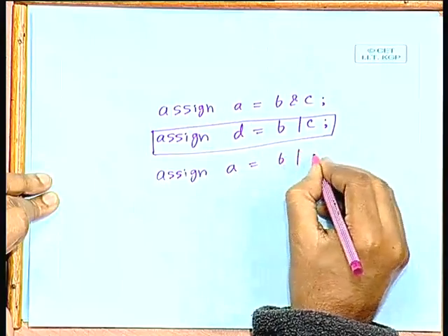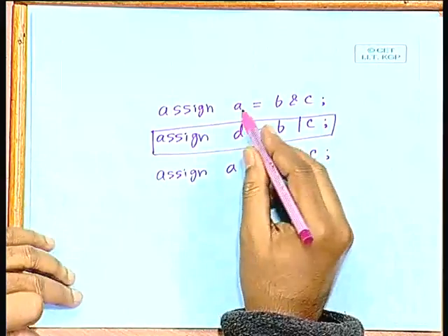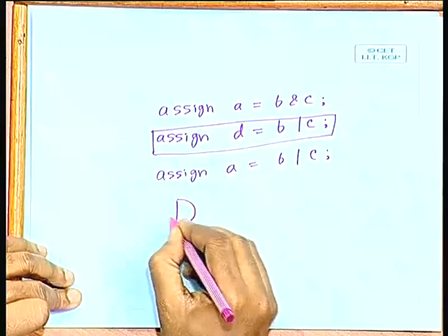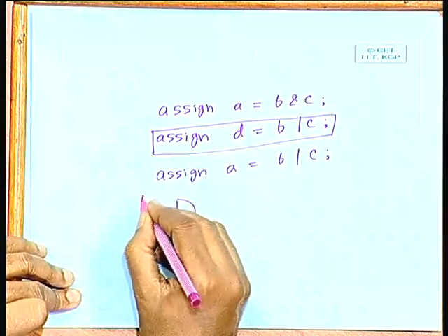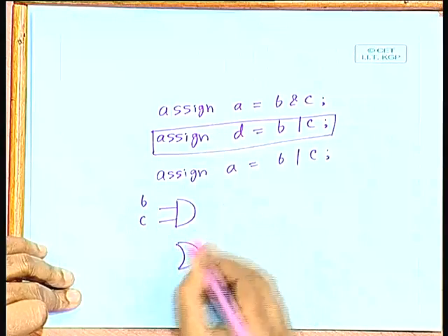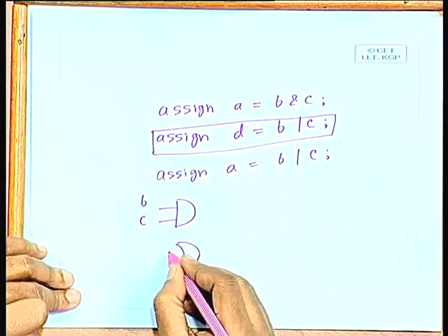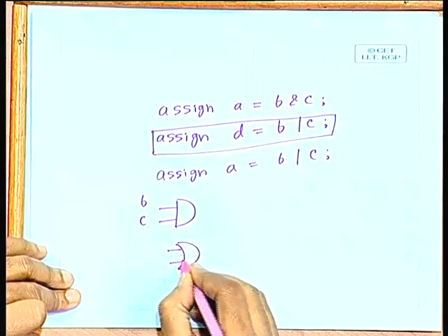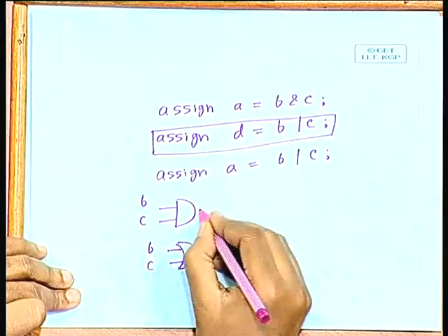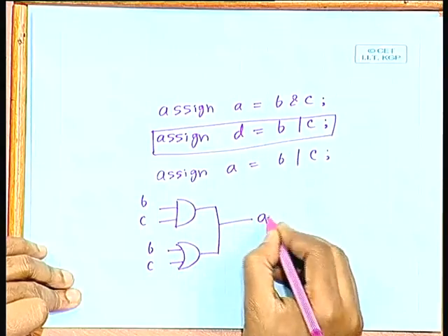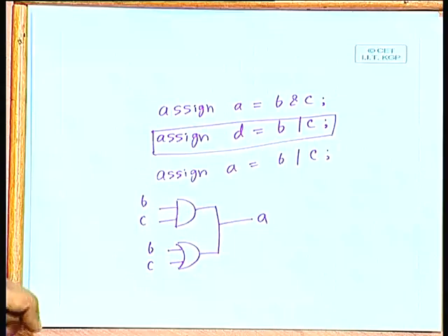Yes, this you can have. This I had mentioned earlier, that this is a net type variable which is driven by two different gates. Now, it is your responsibility to ensure that A is either a wired OR or wired AND, basically a wired type, because essentially this will mean that you are driving this net A from both these gates.